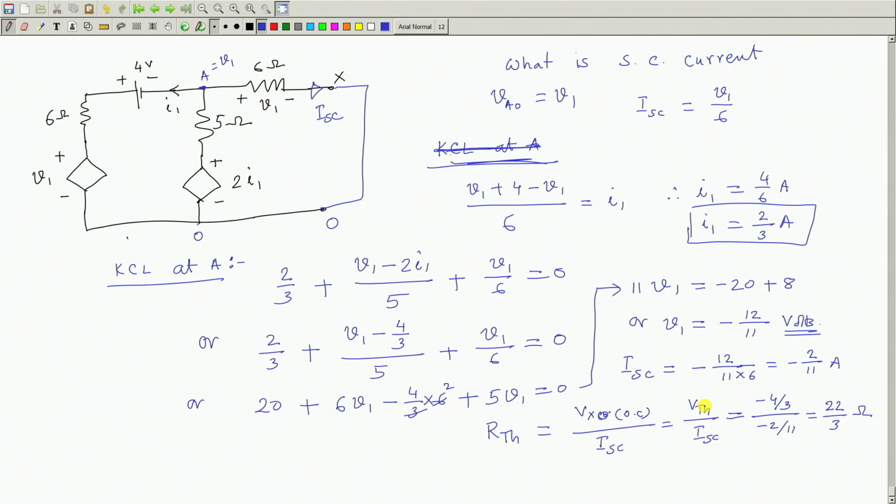So, in whichever way you do it, do it correctly, because when dependent sources are present, this is the challenge. You should be very careful what you are doing. One way of finding currents in any branch of the circuit, do not even go to Thevenin's theorem, you just solve the network as it is. For example, in this network, if I find out all the currents, I have never calculated any Thevenin's. All the branch currents can be calculated by simply writing KVL and KCL. Hope you have understood this.